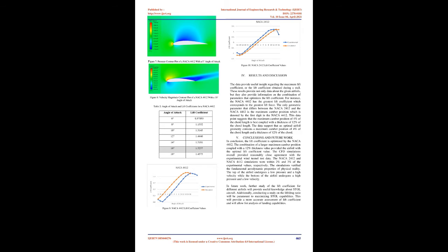Next, a closed volume geometry was created to simulate a wind tunnel. This volume, shown in Figure 4, is created as a semicircle connected to a rectangle. Following this, I created the Boolean, which creates a surface between the flow system and the airfoil. After creating this, the system must be meshed.